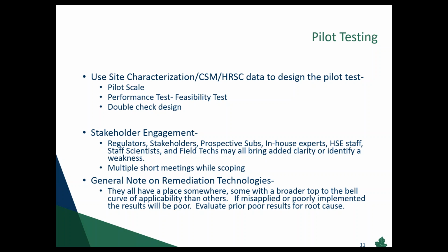So it may be that you do a very limited one or two point test: will this take, and at what rate, and then come back with a performance test or a treatability test. A lot of times you're getting both the feasibility and the performance in the pilot scale. So a lot of folks will do a 3 to 5 point pilot within a certain distance of one well.